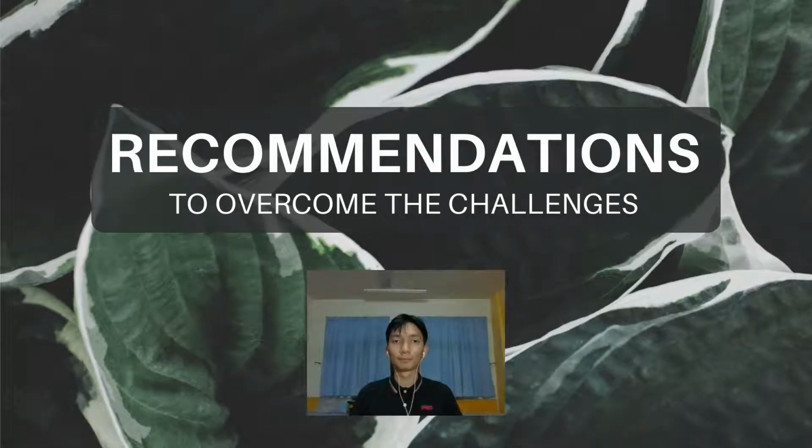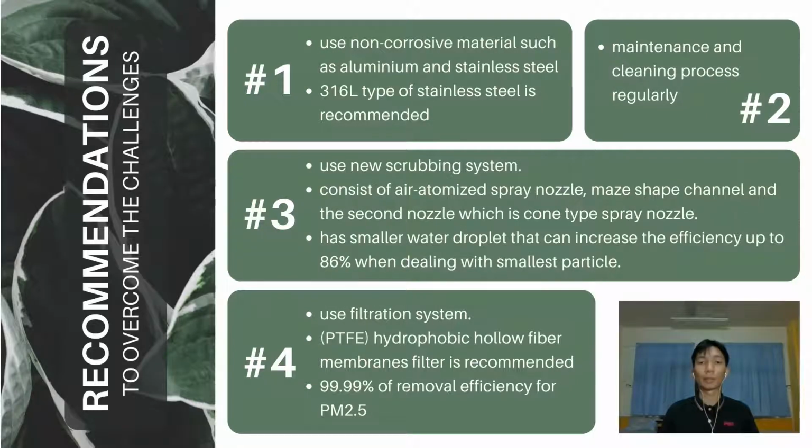Now, let us move on to the recommendations to overcome the challenges. It is suggested to modify all the pipelines and equipment to non-corrosive materials such as aluminum and stainless steel. Plus, cleaning and maintenance processes also need to be done regularly to avoid corrosion problems.